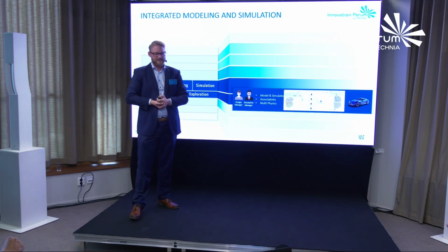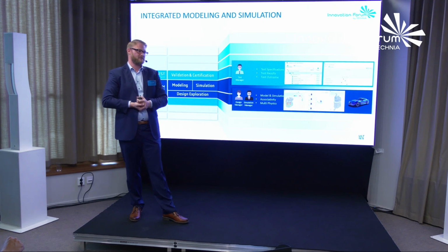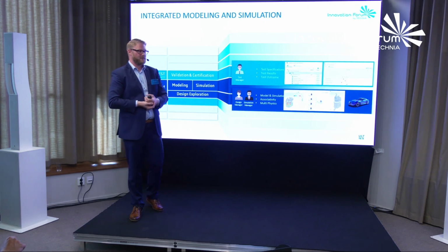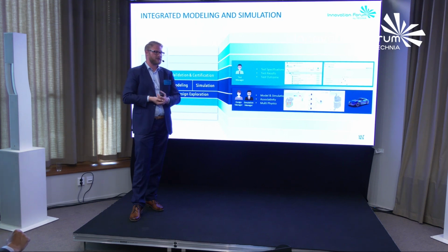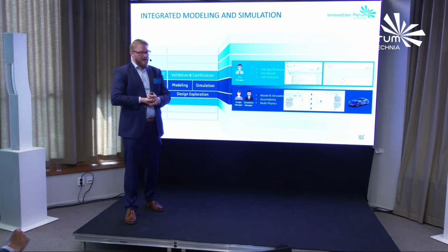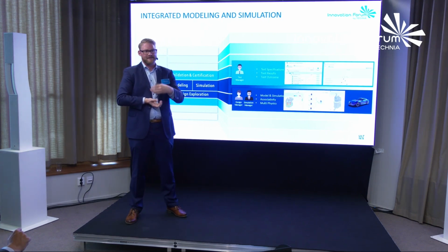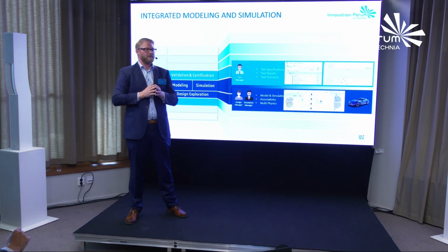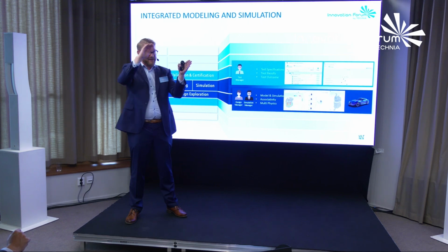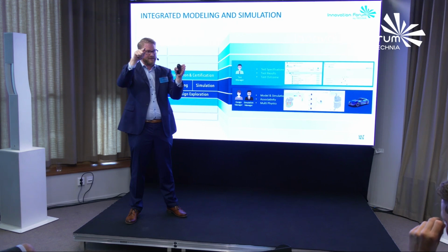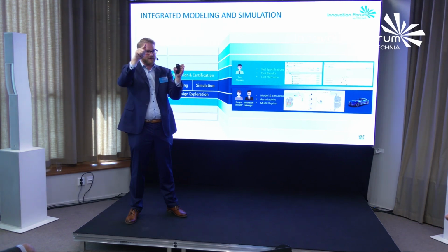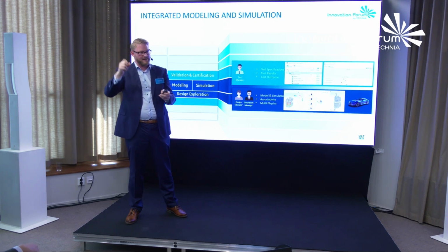Because we're never doing simulation for the purpose of simulation. We're doing simulation because we want to understand what's happening. We have KPIs we want to check. We have requirements we have to validate. And if I have to do that, and I'm having electromagnetics requirements and structures and fluids and whatever, I have to upfront be aware of, okay, what are my requirements? With what test cases can I check them? Okay, eigenfrequency, that's a structural test case. And it's this kind of simulation. Drop test is a different structural test case. Thermal behavior is another test case.